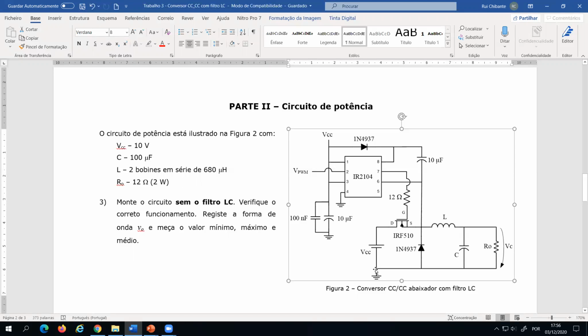Okay, this is the 0. But if I want to apply, let's say, 10 volt as gate to source voltage, I don't have here my 0 reference. Okay, which means that I must work differently. And why? Because the voltage at this node here is floating.